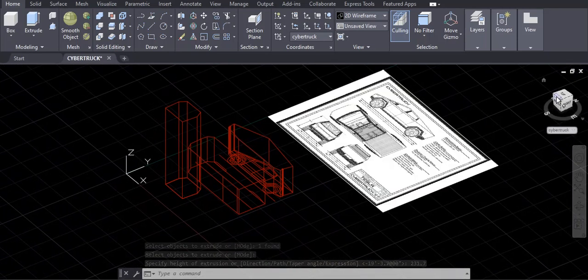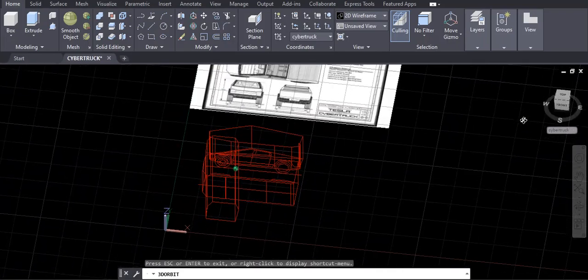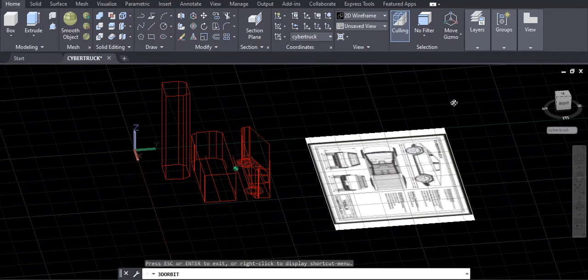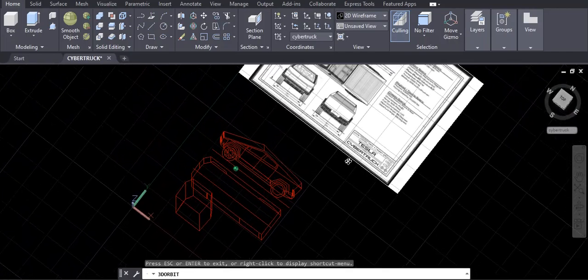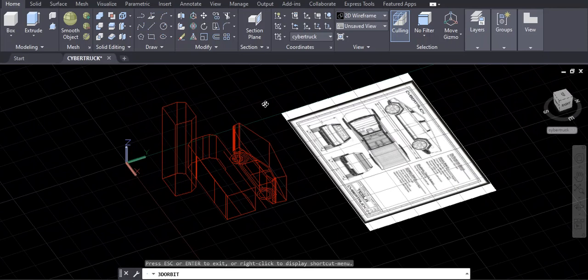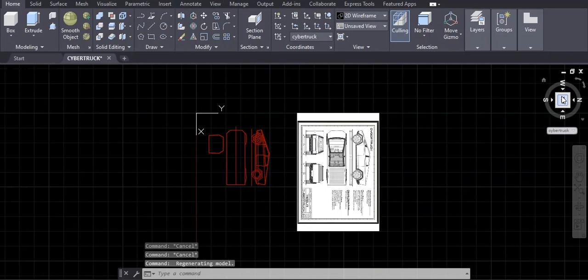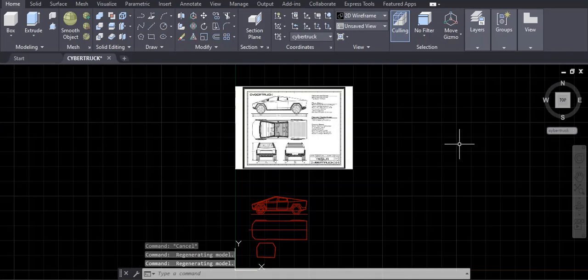Okay, Mr. Ege, what else are you going to do? Why did we do this? And this is obviously not the Tesla Cybertruck anymore the way it is. So why is it that we did it this way? First of all, there's an intersect command that I want to use. Intersect command requires three intersecting solid models, and when you put them within each other at the correct locations, an intersect command will include only the parts that are intersecting perfectly. So this is what we are after.